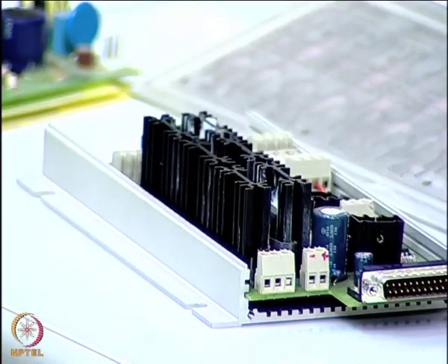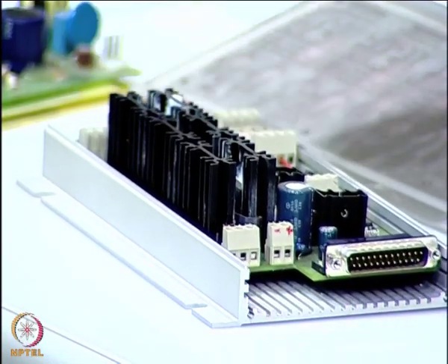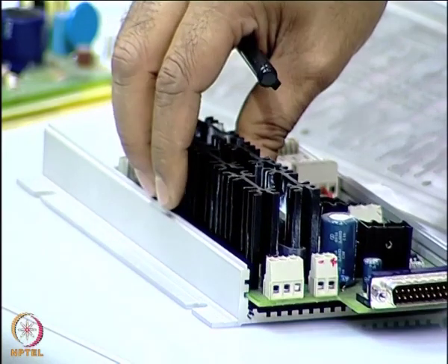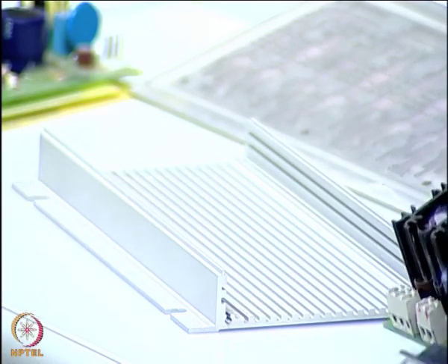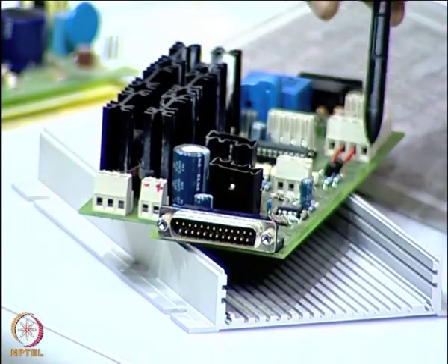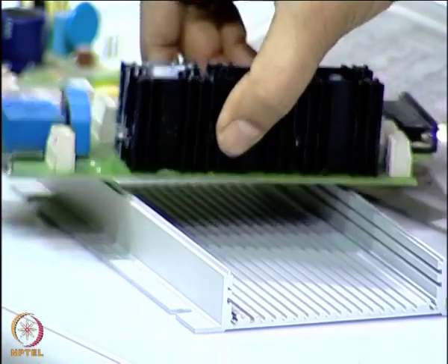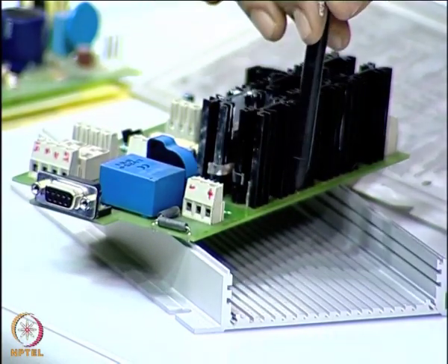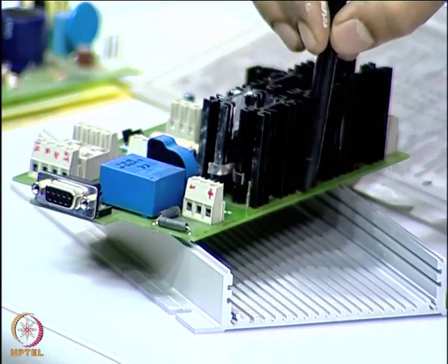Now, these card guides may be metal or non-metallic, but one important thing about these card guides is that you should not have any components for that space of 2 mm or so, such that all this space here and so also on that side, so also on this side where you are going to have the card guide, that amount of space, about 2 mm, should be clear, should not have any components or any track routing on these edges.